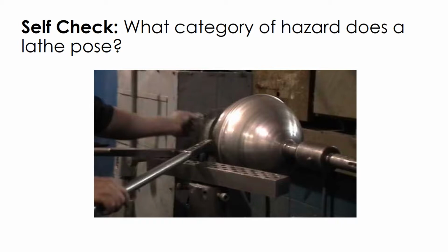The hazard was the kinetic energy from the lathe. This is a physical hazard similar to the risk of a centrifuge. The risk of entanglement can cause a variety of harm, including scalping, limb mangling, dismemberment, or asphyxiation.